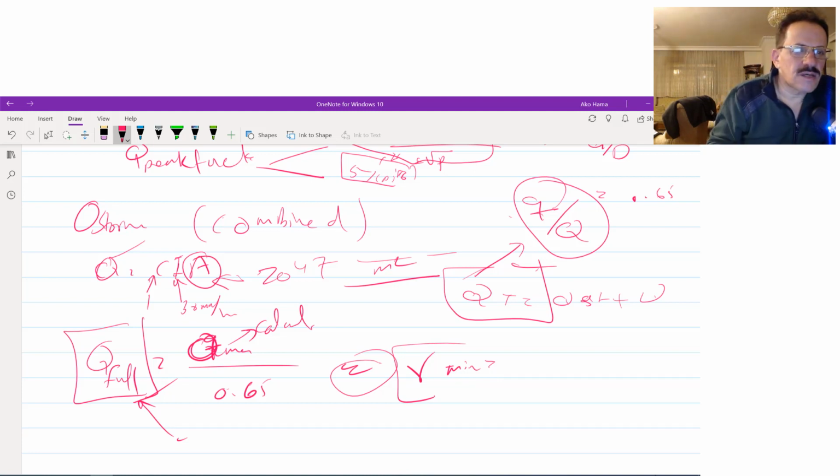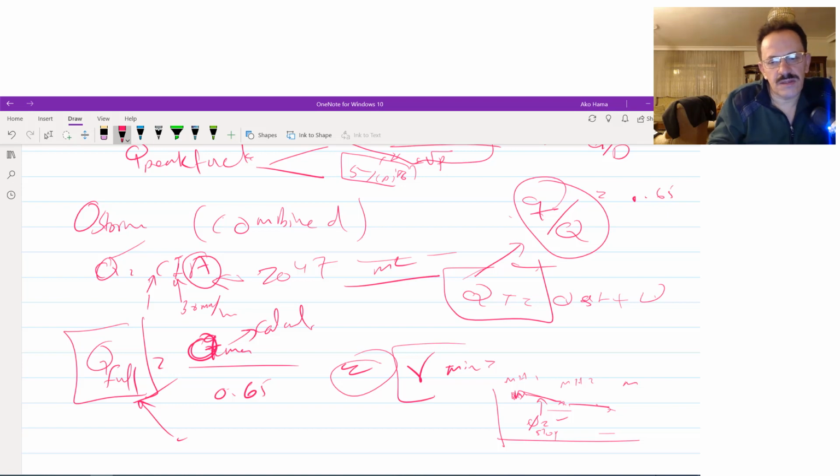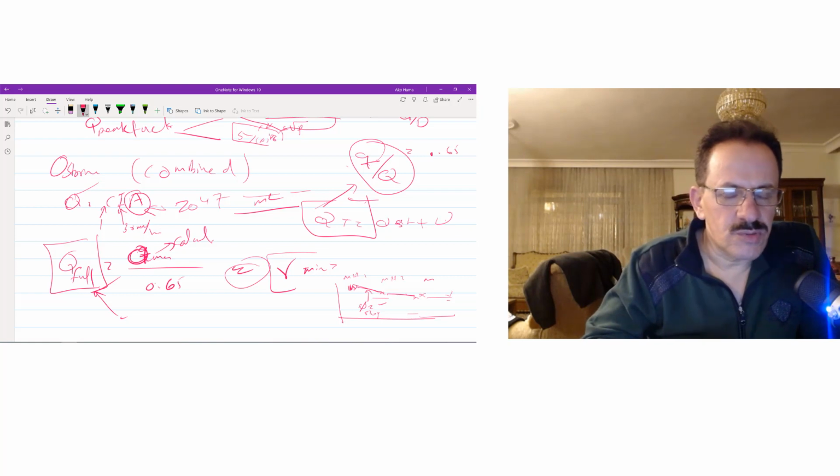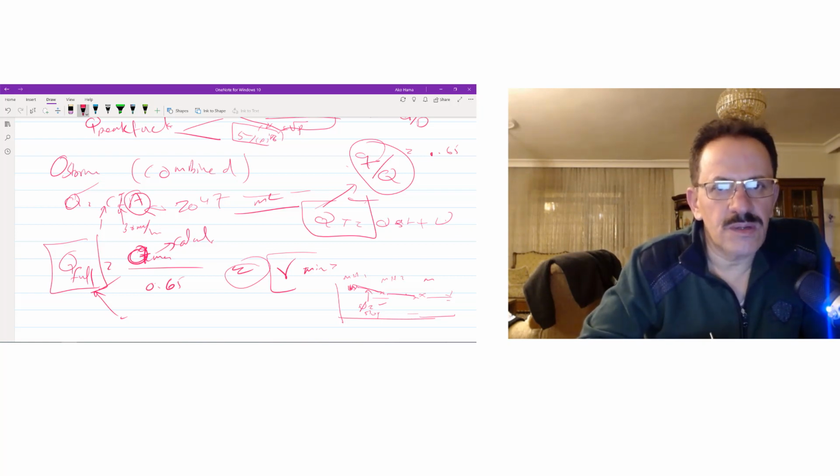You have to do this for all the rest of the pipes. I prefer you to put all the data in one profile, and in the profile you have to find the manholes, manhole 1, manhole 2, manhole 3, and draw the lines between them. You have to say this is the pipe and this is the slope, and then another one, and so on. Don't put more than 4 manholes in one profile.